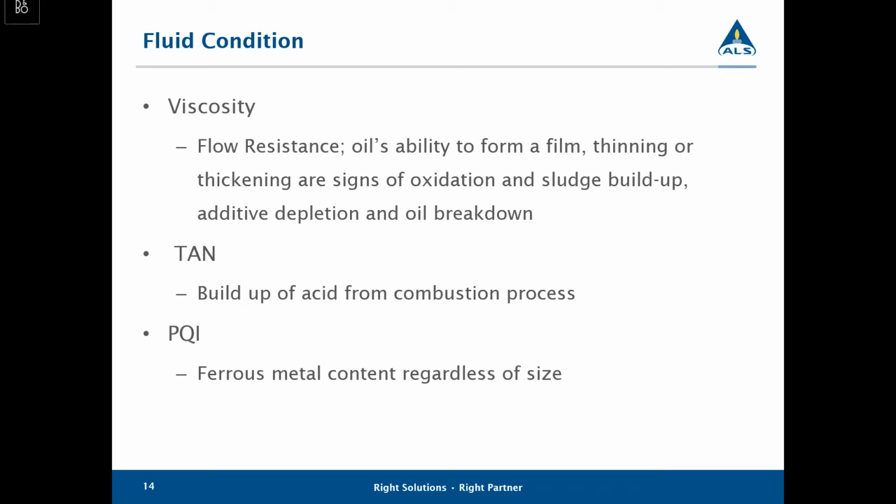Another test that we're doing as well is PQI. It's ferrous metal content, where it doesn't matter what size it is. So the multi-element determination mainly focuses on smaller particles due to their ability to react very quickly in that testing process and emit those atoms. And so if you have larger ferrous particles, you might not get an accurate reading to the true quantity.